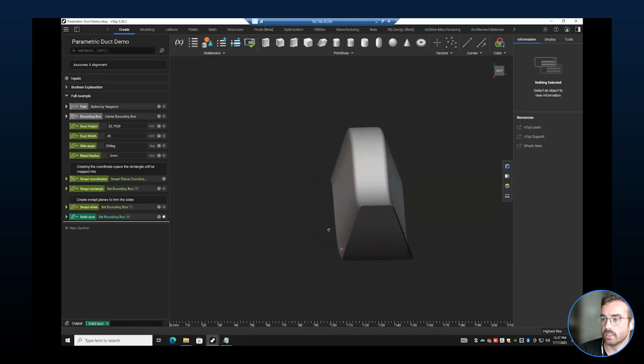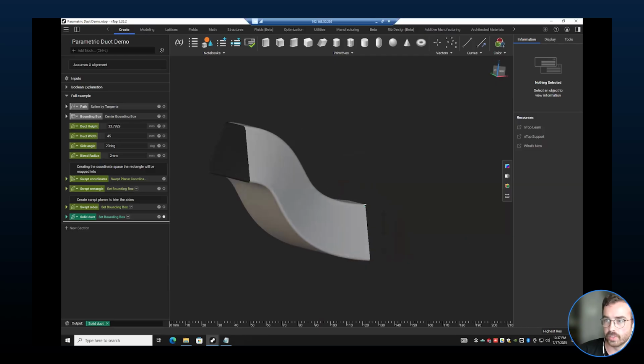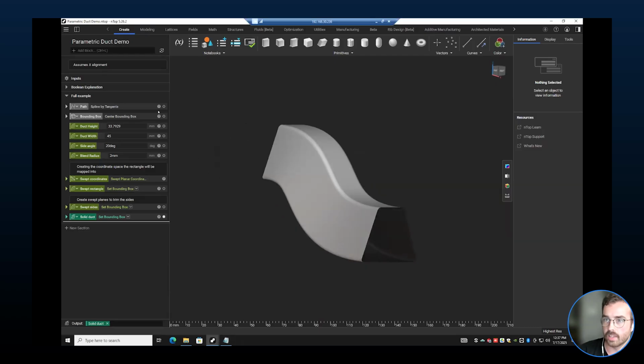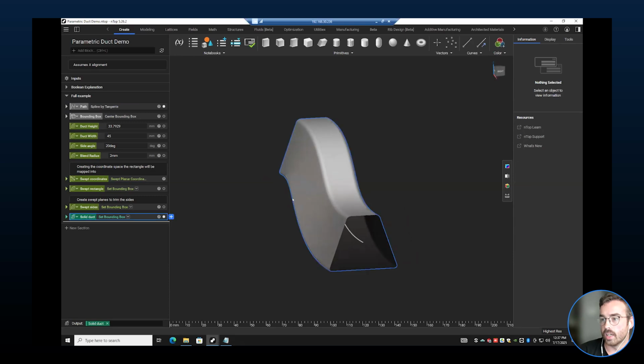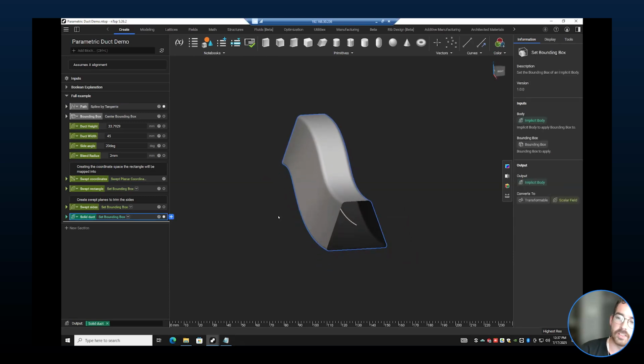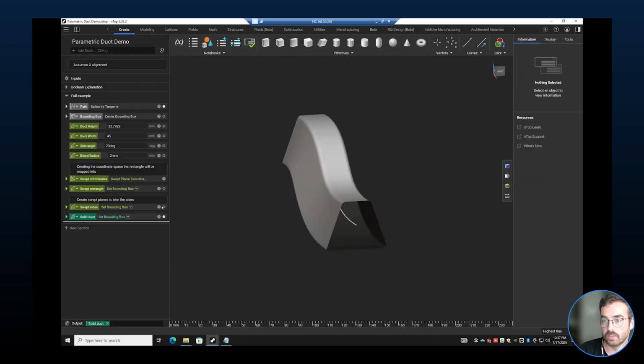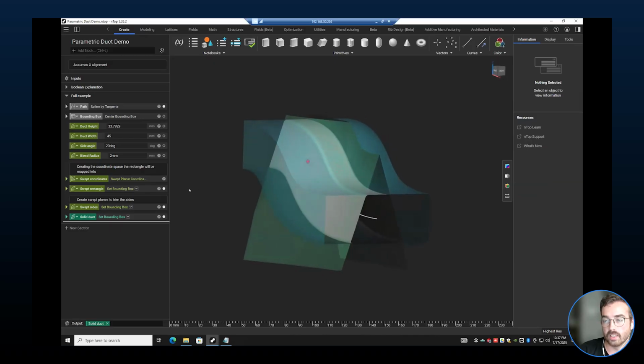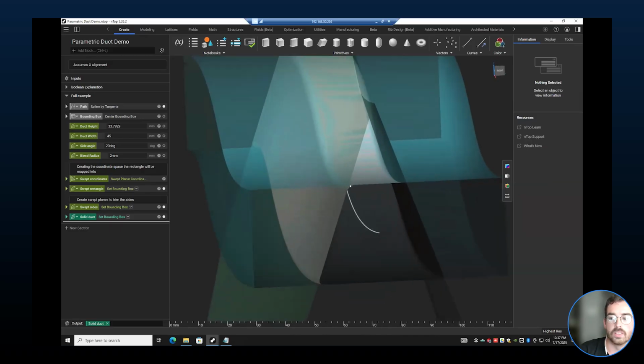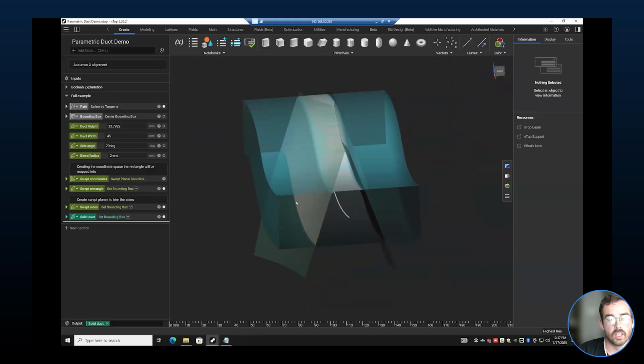So I have this duct here, right? And I have some shape over here, and then some other shape, and then I have a path in the center here. And I wanted to create this shape. You can think of this shape in a bunch of different ways. Maybe a swept trapezoid with fillets added. The way I thought about it was swept sides and then a swept top, and then you intersect those, and then you get this kind of round. And the reason for that is in implicit modeling, when you have something that's rounded or a fillet, you create that at the time when you combine shapes.